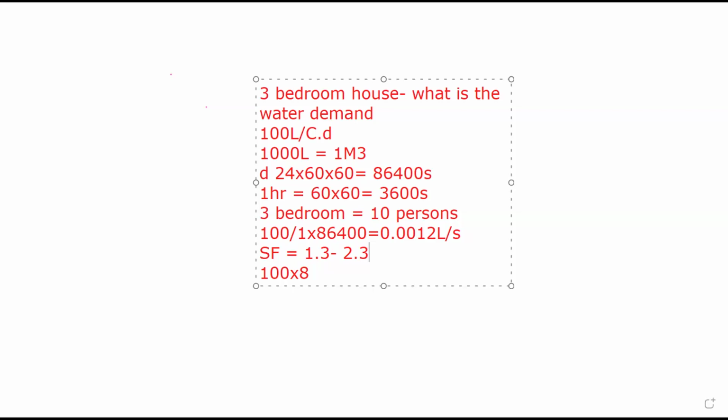In other words, if I'm designing for 100,000 population equivalent, I only need to provide extra precaution for 30% extra. But if I'm designing for, say, 5,000 people, I will design precaution for 100% extra. In other words, I might expect that tomorrow, this 5,000 might become 10,000.